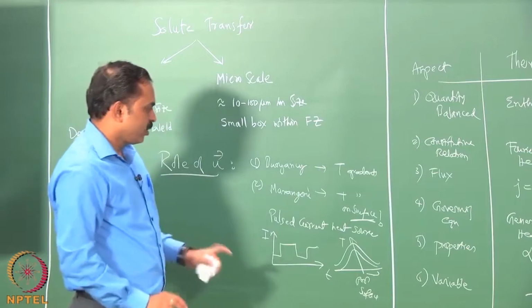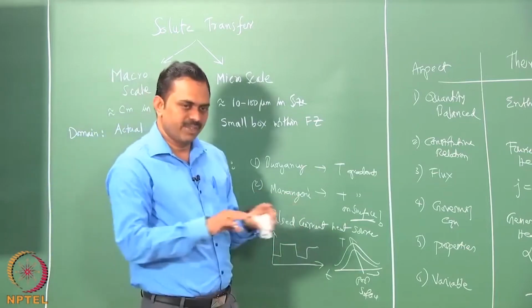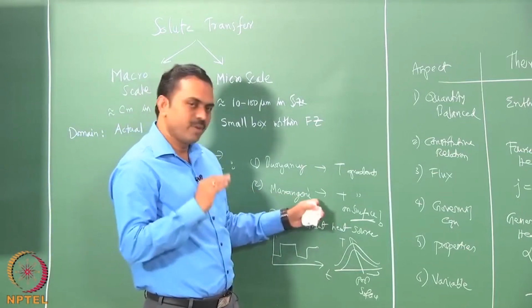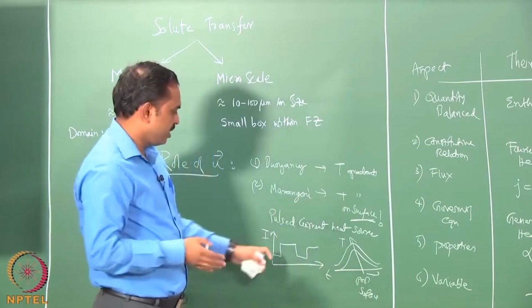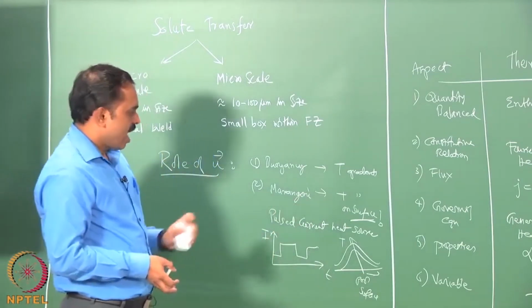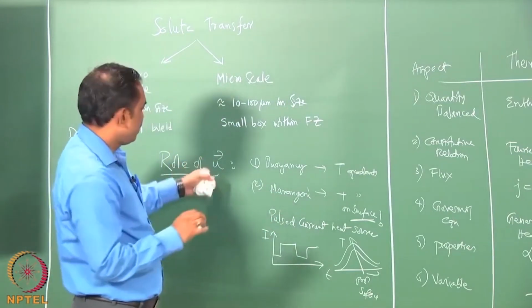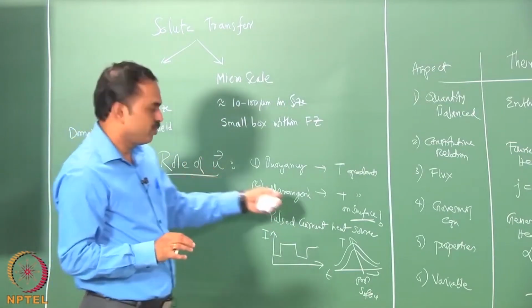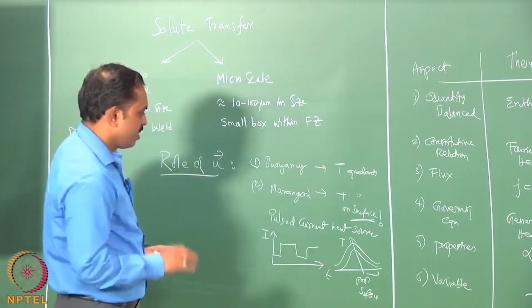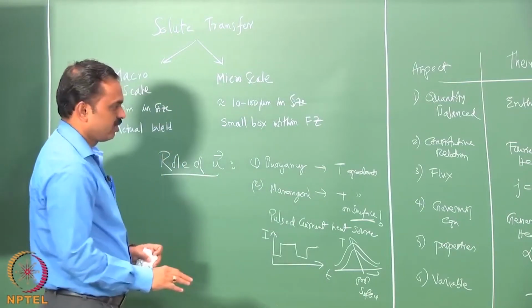So, the Marangoni convection on the very top surface is going to be fluctuating at the frequency at which you change the current, and any fluctuation implies that the velocity on the surface is going to fluctuate by that much variation.